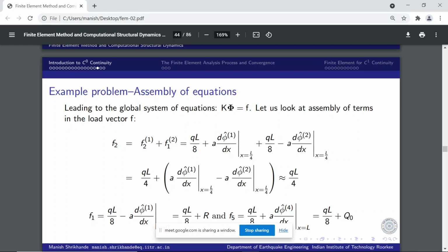How do we decide what should be the size of finite element? How do we decide, take a call, what is a good enough size of finite element? So there is no guideline, a priori, that can answer that question. But once you do a finite element analysis, then you look at the secondary variable, how the secondary variables balance. Ideally, they should be able to balance each other out when you assemble these contributions, but they will not in general.